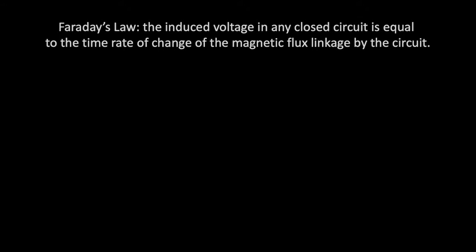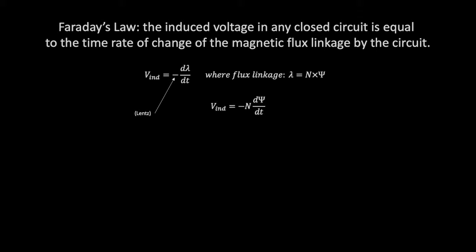Faraday's law states that the induced voltage in any closed circuit is equal to the time rate of change of the magnetic flux linkage by the circuit. Lenz's law dictates this induced voltage to oppose the direction of the flux inducing it. This can be broken down further by defining the flux linkage as the number of turns in the circuit times the flux through each turn.